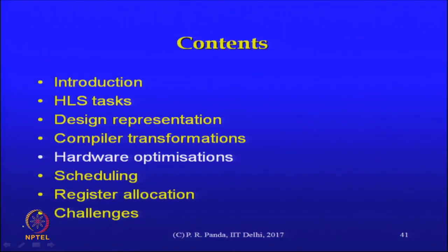We will look at a few other optimizations that could fall in the category of hardware specific optimizations. These might not make obvious sense in the context of compilers. Sometimes it might, but usually it might not, but in the synthesis context it definitely does. We still haven't started with the actual synthesis tasks, which would be the scheduling, register allocation and so on, but this is still a pre-processing of the internal representation. But this keeps in mind the fact that the target is synthesis and not compilation.